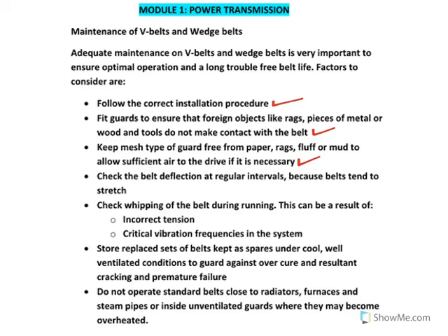That is, make sure that whenever the belt is in operation and it is covered inside a mesh, that area must allow air to come in and out so that it can cool. Check the belt deflection at regular intervals because belts tend to stretch.